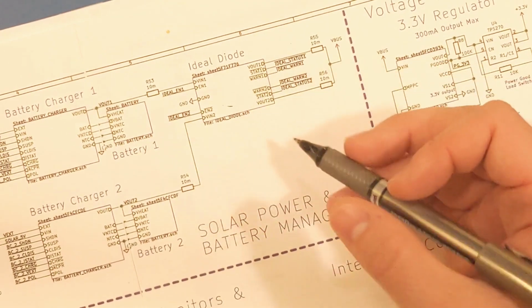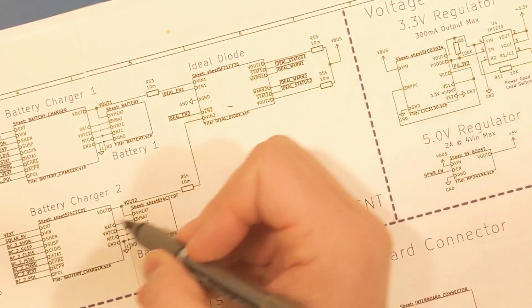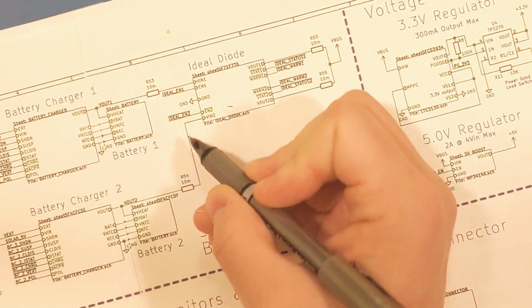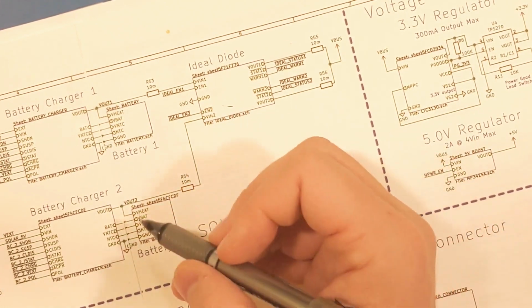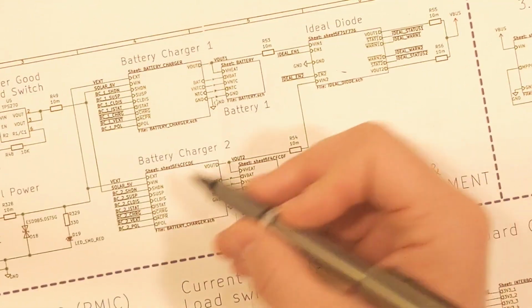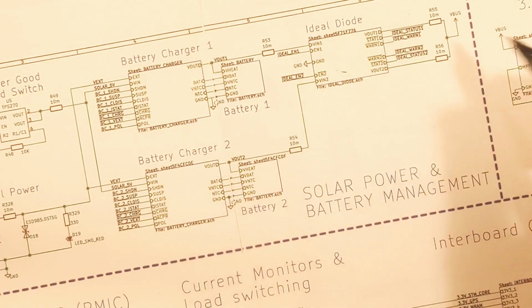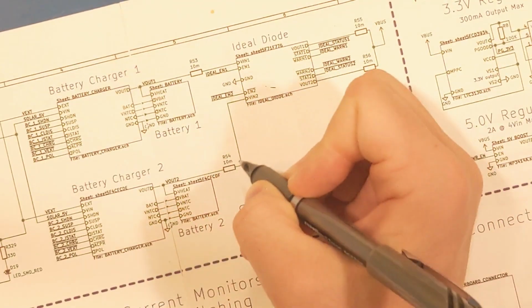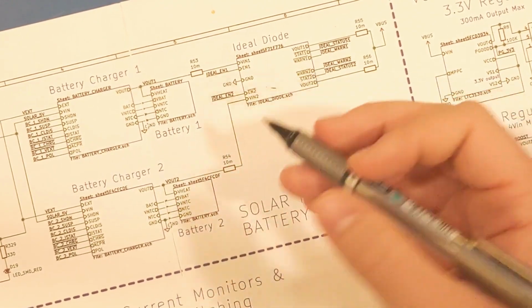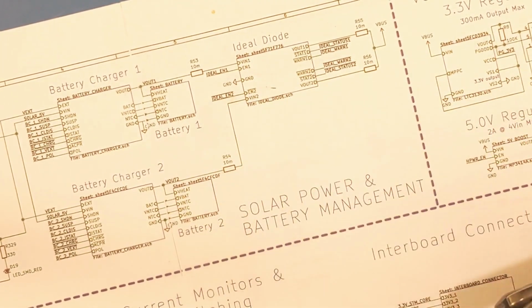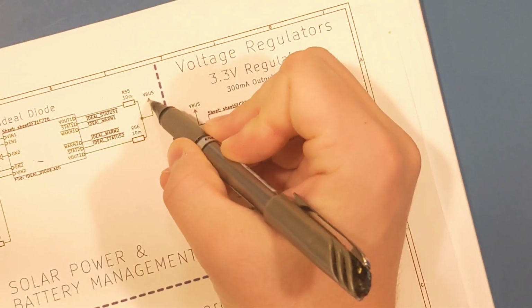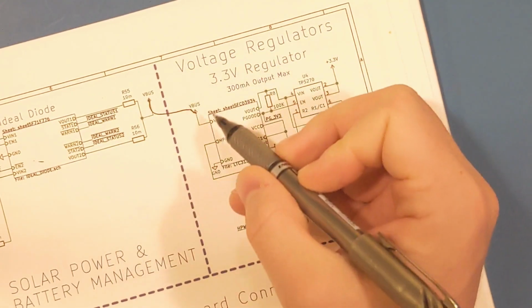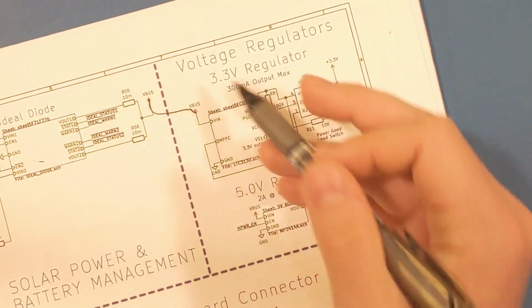So I can break a circuit if I know that something isn't working down the line here. I can just remove this resistor, and now I have eliminated this circuit entirely from causing any issues. In theory, in a final build of whatever I'm doing, these resistors would go away, but right now they're really useful for development. So V-bus goes right here, right to here. And that's the only place it shows up on the schematic.